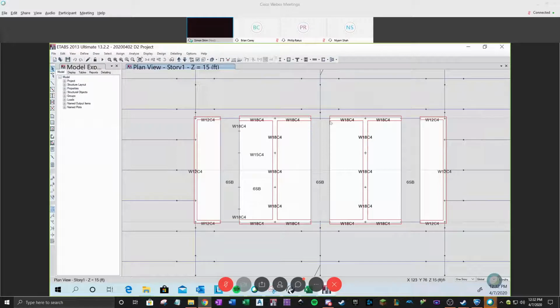When you see the I-shaped flanges, this I shape of the wall has a moment of inertia. The flange thickness really plays a very big role in stiffness, like a steel section, same mechanics, especially moment about the strong axis of this I shape.